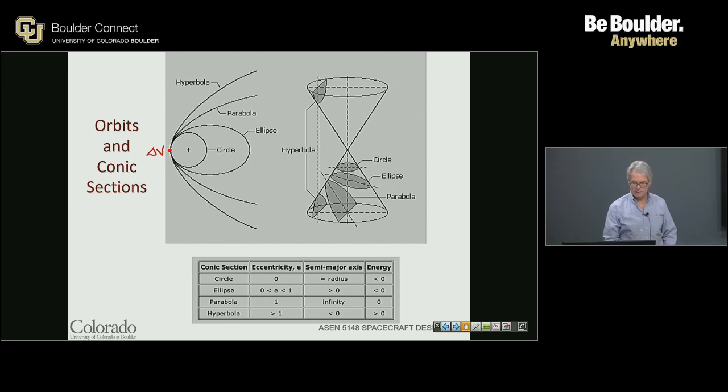If we would do the same thing as the spacecraft came around and add a velocity change at this point, we could put the spacecraft on an outbound trajectory that takes forever to get to infinity. This is called a parabolic trajectory. Parabolic trajectories are interesting because they're, if you will, the cutover point from a closed orbit, an elliptical orbit, to something that has some additional velocity put to it, and that's known as a hyperbolic orbit or a hyperbolic departure orbit.